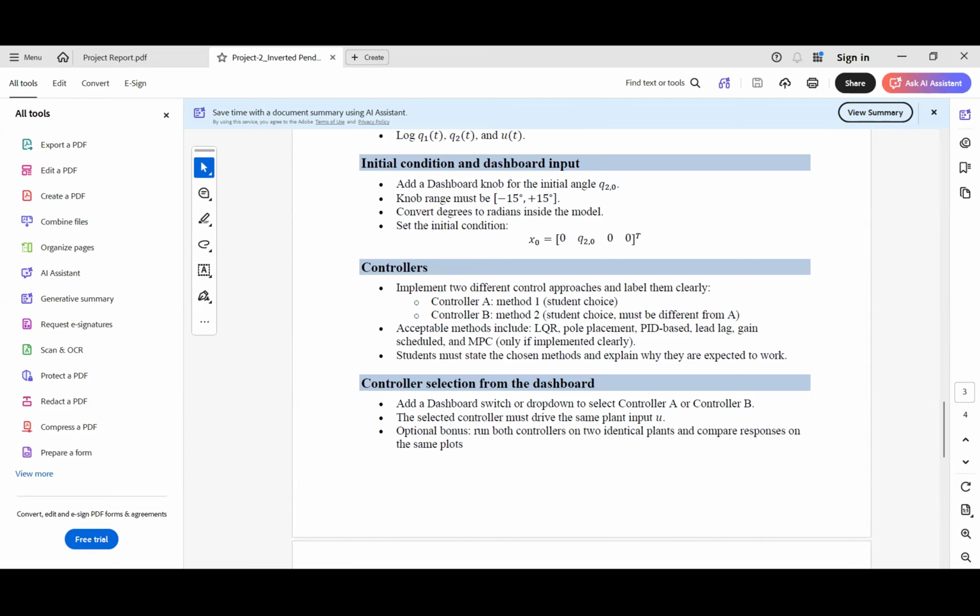After that, we have the output from the plant. We split the value using the demux, so Q1 and Q2 now come outward from here. This will give you another scope for Q1. Here we have changed the value into an absolute value, which gives you a positive value, and it will be stored in this memory. This stored memory will go into the dashboard we have displayed here. All the graphs will show here, and all the peak U values stored will go here, and the Q1 value which is stored here will go here, and the Q2 value will go, I'll show you where the Q2 is.